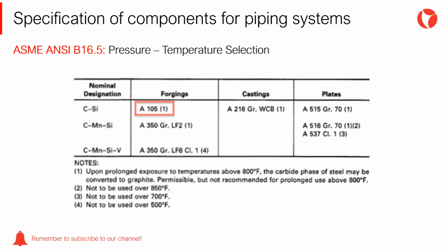These flanges have standardized dimensions. They have been designed to withstand specific design conditions, pressure and temperature range. That is why they are not calculated, but selected. Flanges up to 24 inches nominal pipe size to be used in piping systems must be selected from the ANSI B16.5 standard.